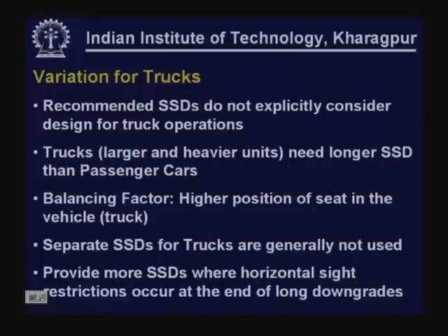Now, variation for trucks. The recommended design values for SSD, particularly the AASHTO recommendations, are based on car traffic movement. They do not explicitly consider design for truck operations. Now, trucks, especially the larger and heavier units, need longer stopping sight distance due to the vehicle characteristics.